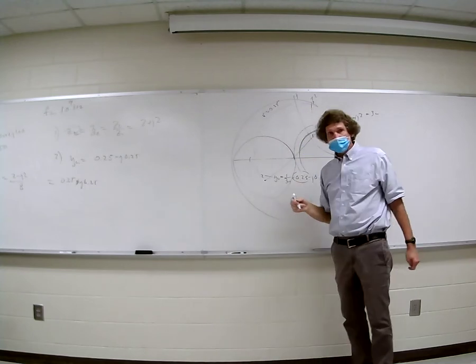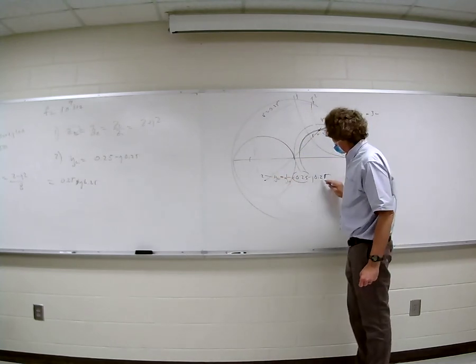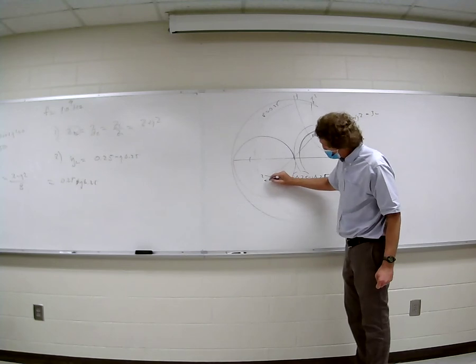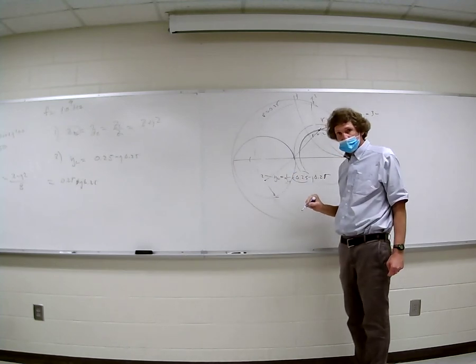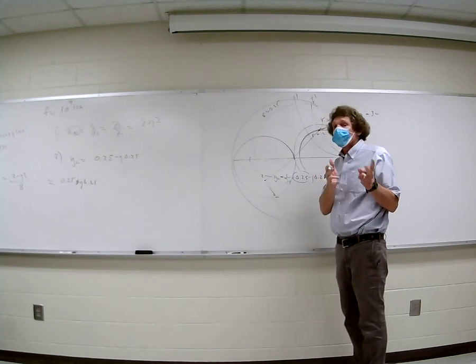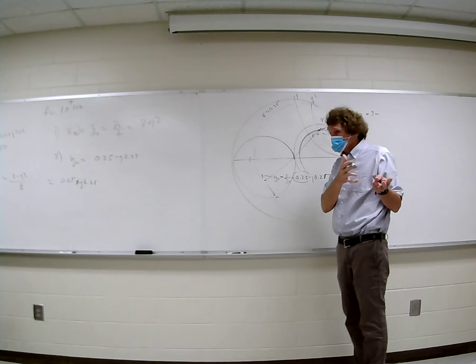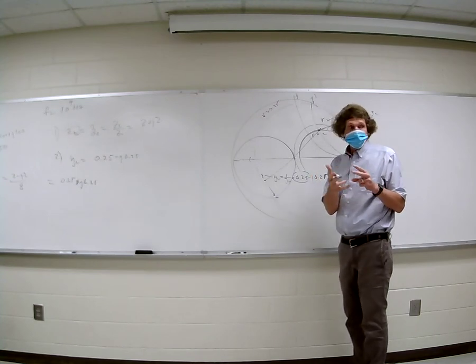Something like that. You agree? Now, anytime we add reactances, we're going to increase or decrease that minus j 0.25. We could add this way and come to this point, correct, class? And here's the thing. If we're adding admittances, positive admittances are capacitors: positive j is capacitor, negative j is inductor, all right?